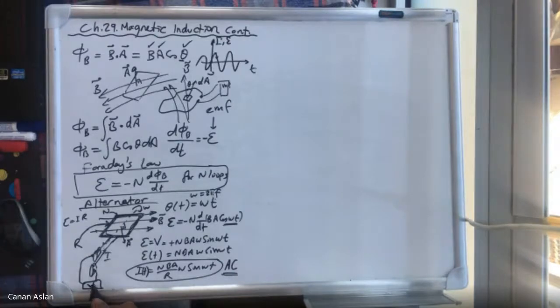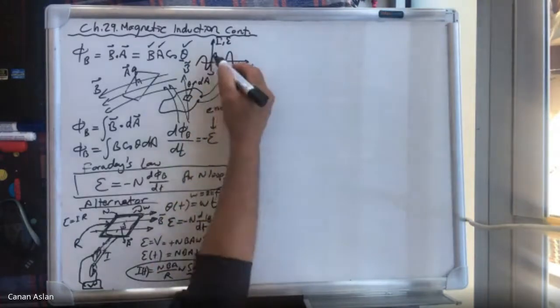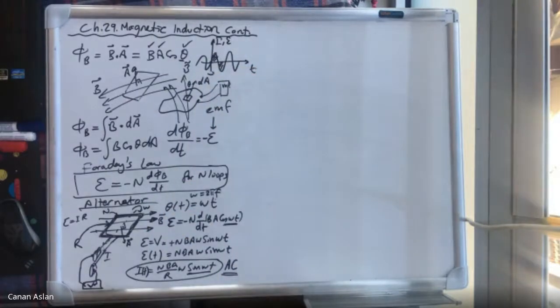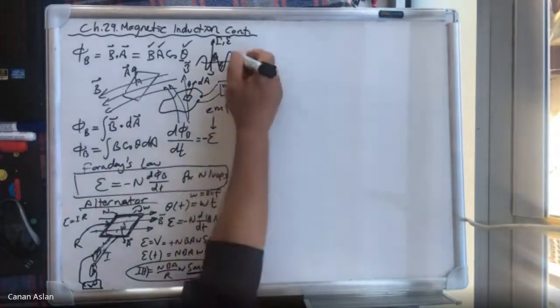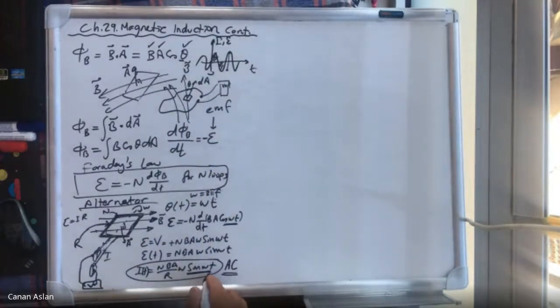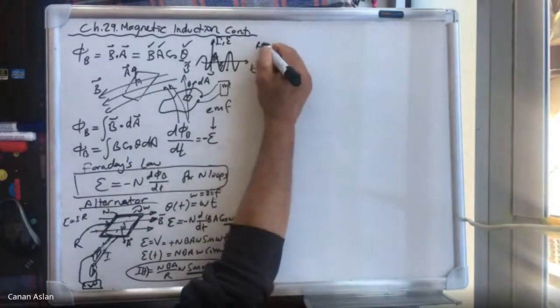But if you want to connect this to a multimeter, these AC voltages are measured such that RMS values are obtained. What does it mean? Because if you take the time average of sine omega t, it's just 0, because there are some plus and minus parts. If you take the average of this, you get 0, basically. But if you want to get something measurable, related to peak voltage like that, you get the RMS of this value. Okay, what does it mean? RMS means that